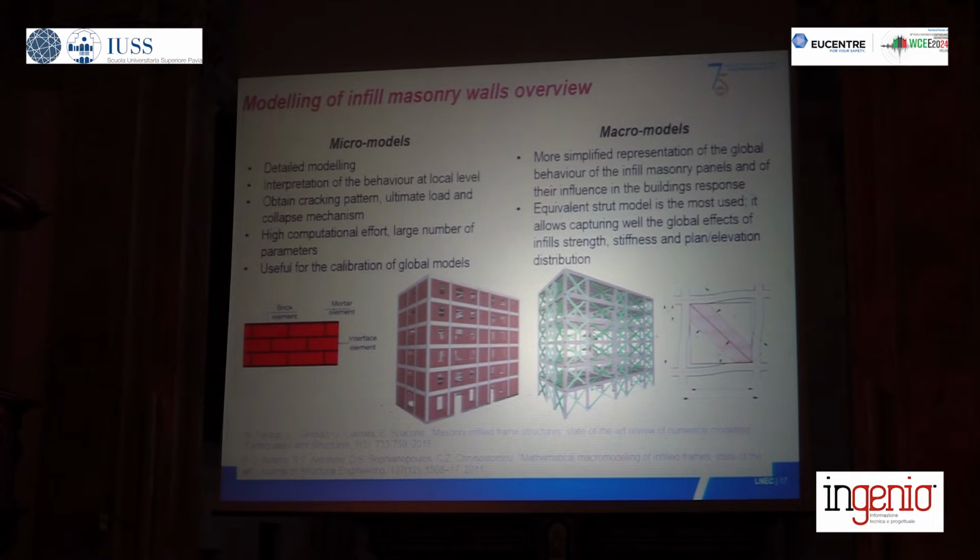Now, looking at the modeling of the infill masonry walls, just giving an overview of the type of modeling, we can go to micro models and go into the details if we have enough data to calibrate and to validate the parameters that we use on the model. But typically people are using macro models to model the global response of a reinforced concrete frame with infills, which allows to capture well the global response of the structure.